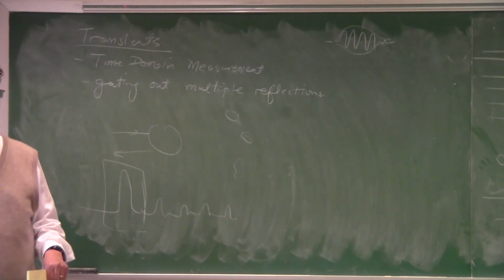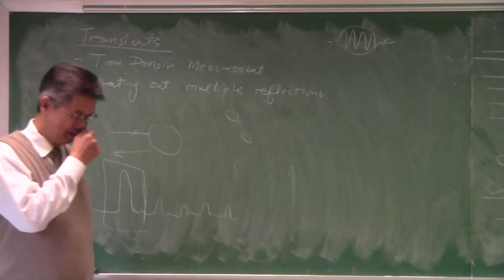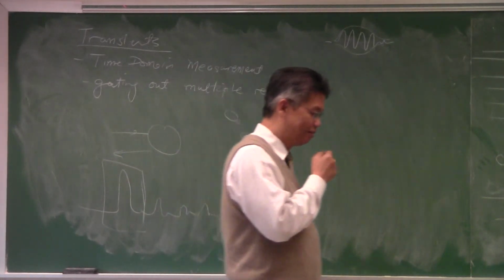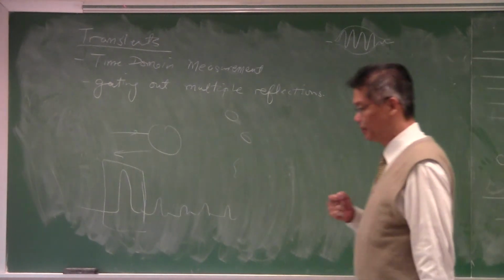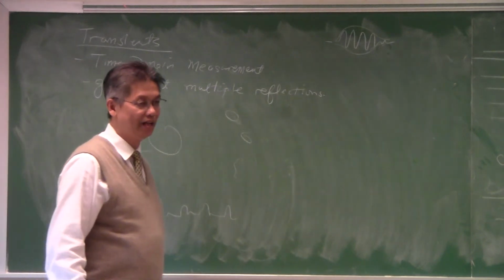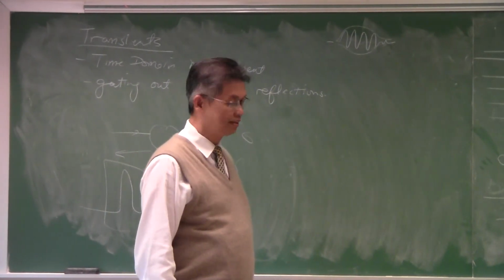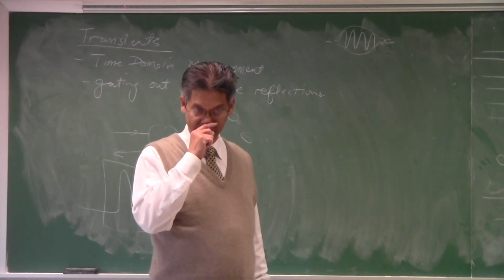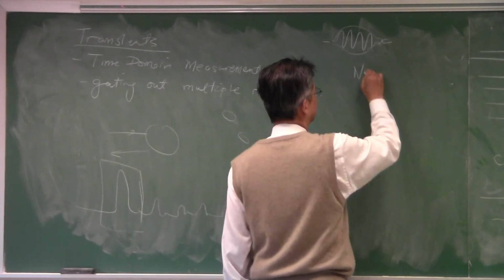Because you can average out noise and do a bunch of frequency measurements to reconstruct the sound. That's right. Very good. Okay. Measurements in the lab, you have the liberty of measuring over a long time. And because you have the liberty of measuring over a long time window, you can make your measurement as accurately as possible by doing time averaging. That's one thing. By doing narrowband filtering. Okay, narrowband filtering.